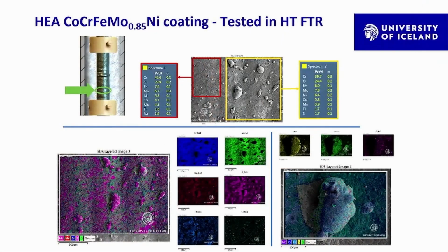So there has been some droplet formation instead of complete melting of these particles during the deposition. And we saw some sulfur products more evident in these globules. Our approach was to test it as received, with no surface treatment of the coatings before the tests.